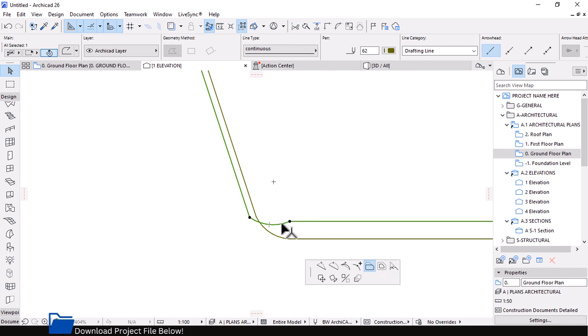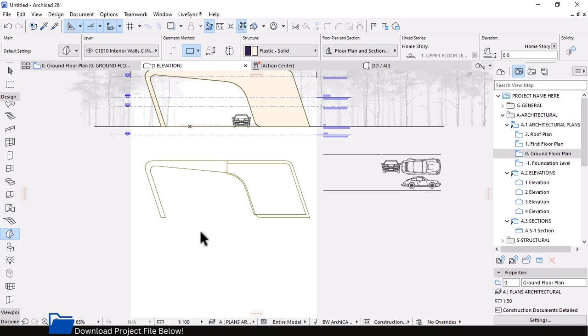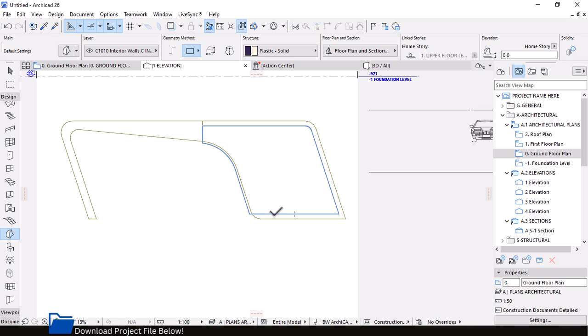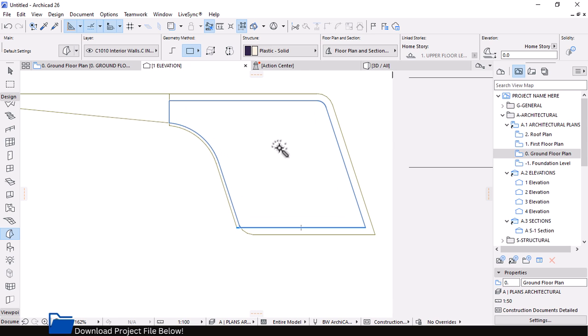So this is going to be just a line. We're going to convert it into a straight line like that. Let's fix it here, fix it there, and then move this point to this point. Perfect. Let's pick our morph and do the same. Hit the spacebar on your keyboard to activate your magic wand, and make sure you select around this time, because there are lines on top of each other. We want to select the line edge instead of the region, because you can see the difference. If you select the region, it excludes this part we want to include. So it's best to select the curve or the edge of the line, and then click to apply your morph plane.